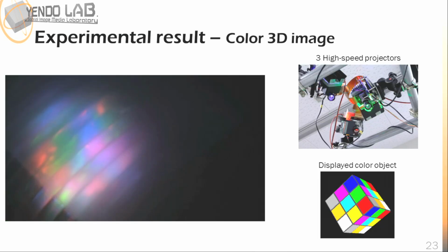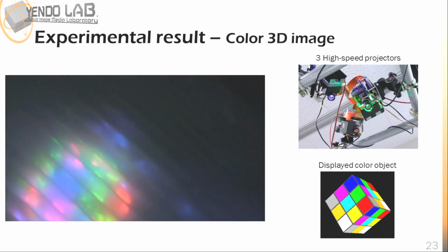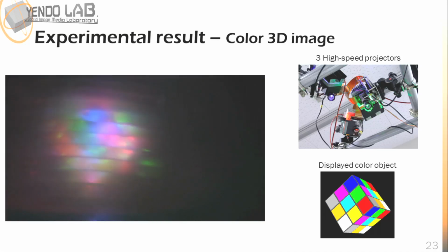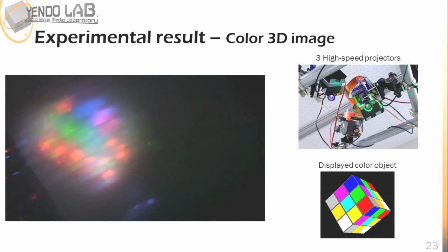We also developed color display based on the proposal. Normally, DMD projectors employ a color wheel to display color images based on time division multiplexing. The proposal tries to convert time division resolution to a directional resolution of ray. Thus, we employ separate red, green, and blue DMD projectors for color images. However, the color of tiles is incorrectly observed. The difference of optical axis causes this phenomenon. The transition of parallax shifts between each color.